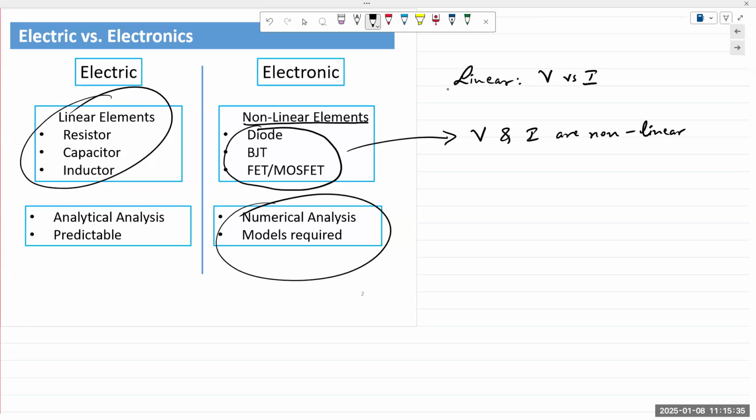we find out the answers. And once we have an answer, we verify with our assumption at the beginning. Meaning, if we assume that a voltage has to be within a certain range, we make that assumption, go through our analysis using that method, find out the values. At the end, we compare the value with the assumption that we made at the top. If it matches up, great. If not, we change our assumptions and we redo the analysis. We keep doing it until the end result matches up with our original assumptions. And that's basically numerical methods in a nutshell.